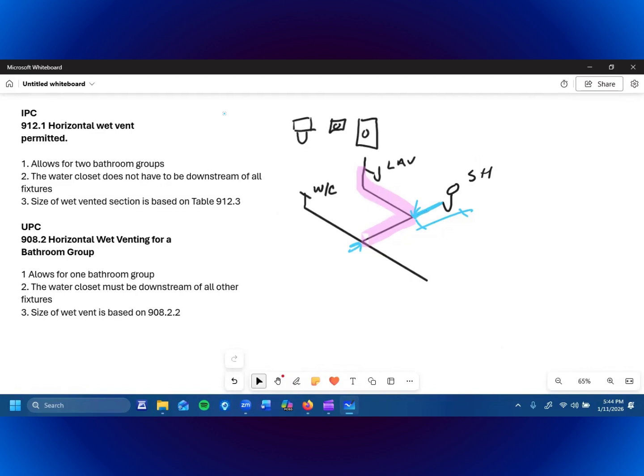What is that maximum distance? Anybody? It's rhetorical. There's nobody but me on the thing. Sorry. So, 2 inch maximum in the Uniform Plumbing Code, 60 inches or 5 feet. That's the maximum distance there to where it can tie in.